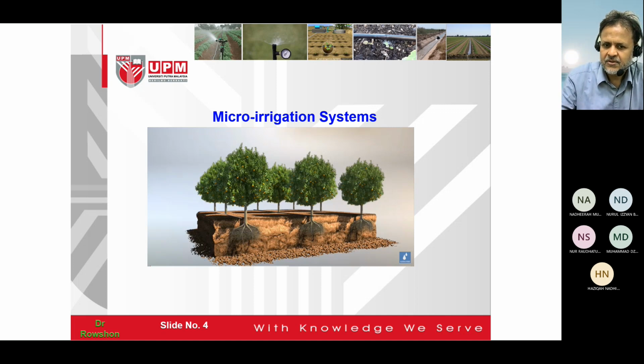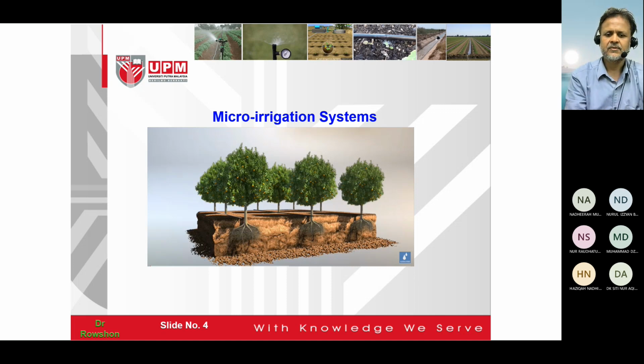And we know that the crop takes water by the root, not from here. If there is no root, the crop will not take the water. Water is here, but if no root is here, the crop will not take the water. Almost 95% or 98% of roots are here. Maybe a few roots can move here, that is negligible. So we will consider most of the roots accumulated within the small area. In that case crop water requirement equals ET. I think this is appropriate when we consider climate-based.